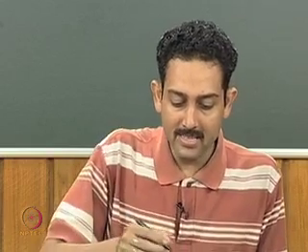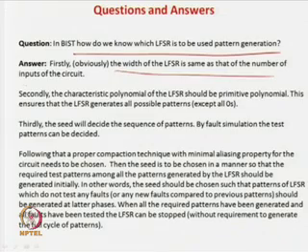First, the width of the LFSR is the number of inputs of the circuit, which is very obvious. If you have an n input circuit, then n bits are required in the LFSR. Secondly, the characteristic polynomial should be a primitive polynomial so that it generates all possible patterns. In most cases you would require all patterns to do the testing, so you can go for a primitive polynomial, but there are also other cases, since all zeros cannot be generated, as we will see very soon.